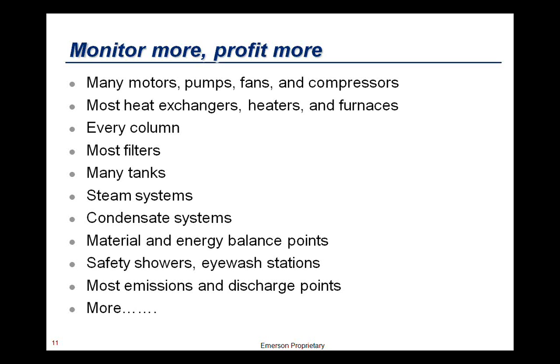Electric motors. Today, as they have for many years, have temperature sensors even in the windings of the electric motors. Do we connect up those sensors? So often those sensors are left unconnected, and therefore valuable information that can provide safety on the plant, better return on the investment, and that we don't lose the pump or the fan or the motor that's there.